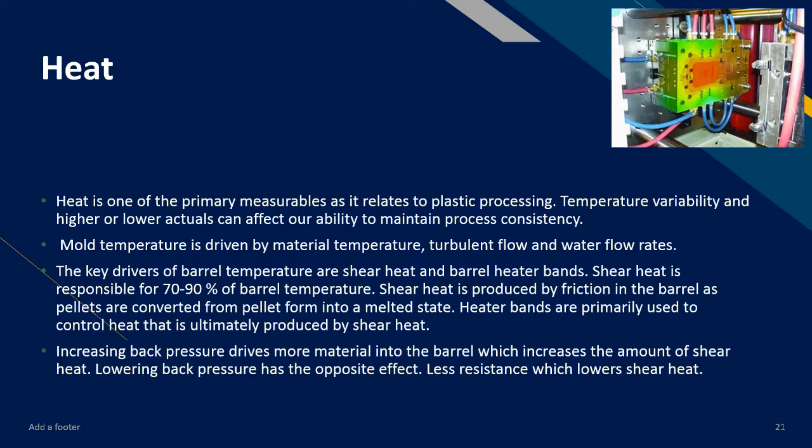Now, by increasing back pressure, we drive more material into the barrel. This increases the amount of shear heat through resistance. Lowering back pressure has the opposite effect, less resistance, which lowers shear heat.